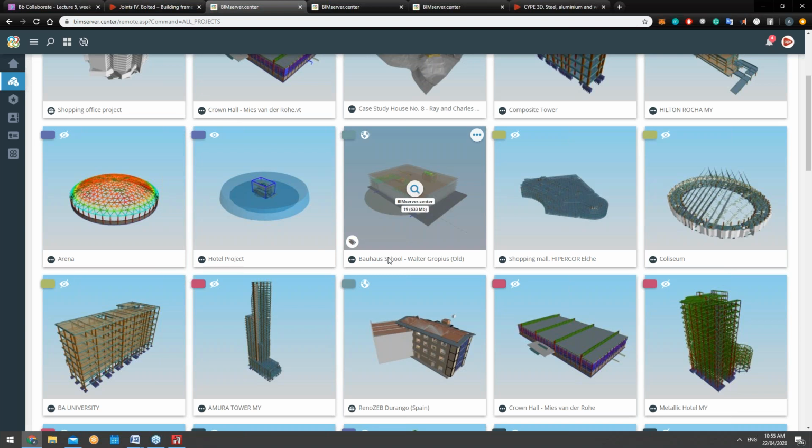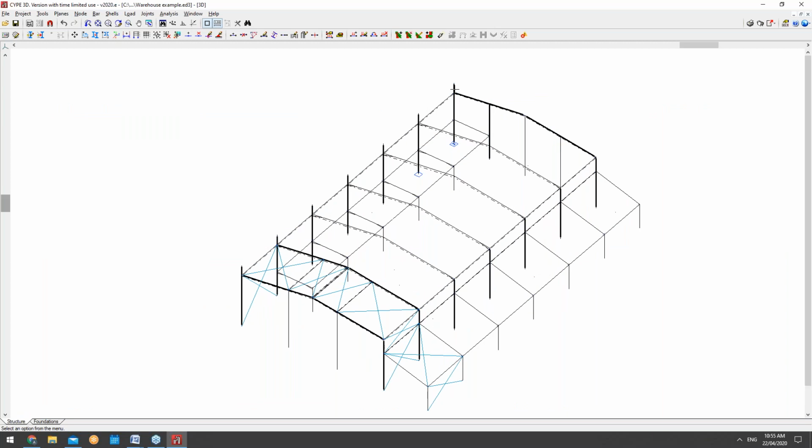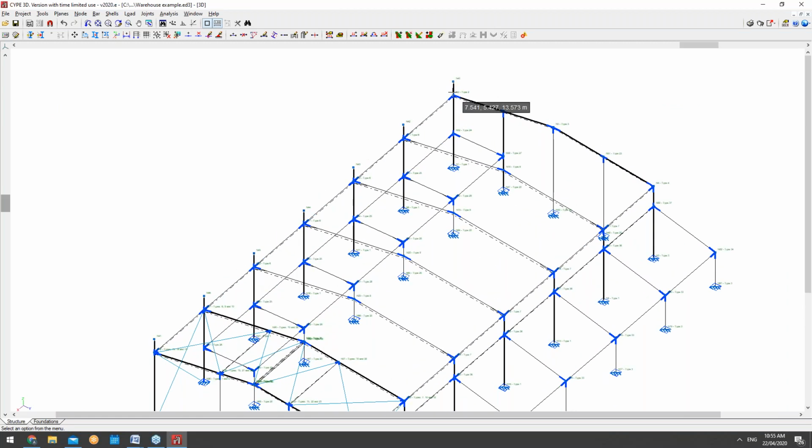Ahmed's asked something about his request for tube or boxing connections. The thing with tube and boxing connections is you can do it if, one, they are simple connections, and two, they are all boxed connections, not a boxed coming onto an I-beam or a box connection coming into some different types. If you've got a simple box connection, you should define the connection as such.